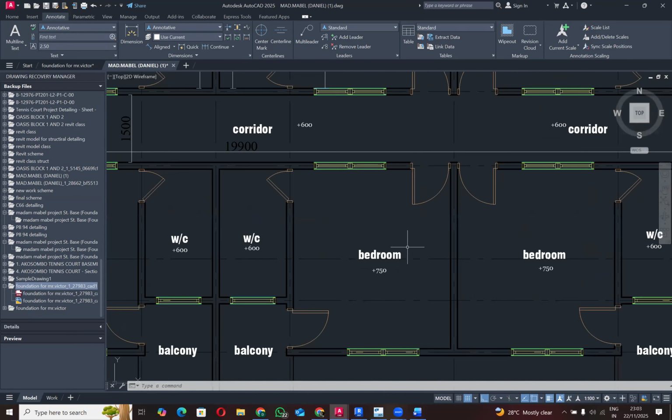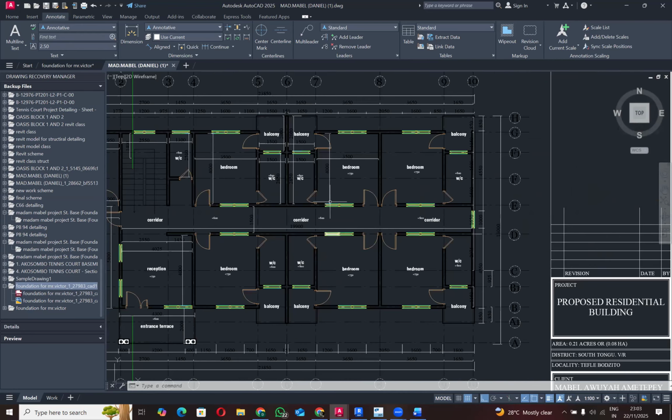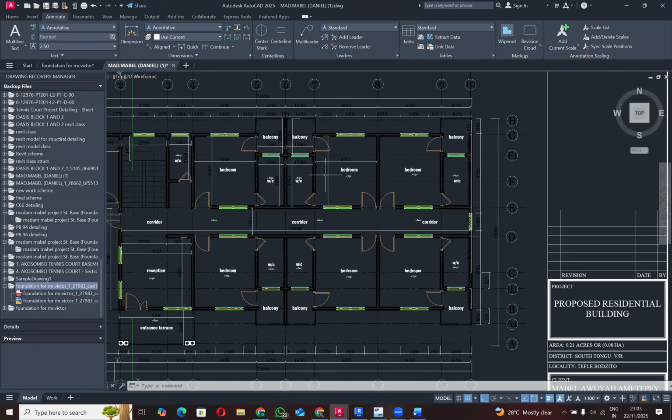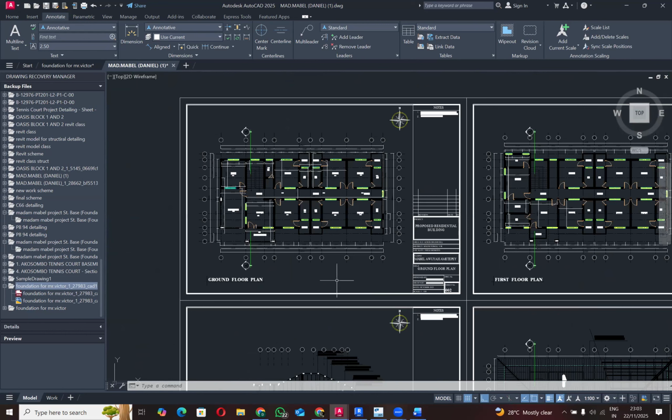If you put in a model that meets those architectural elevational differences, you also have to look at your structural requirements, where you also focus on what the designer has given to you. The designer has given to you all the structural elements, their sizes, and also the detail requirements, which include the reinforcement type, the count number of each of these reinforcements for each of the structural elements, and then the spacing that you have to follow through.